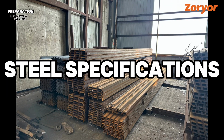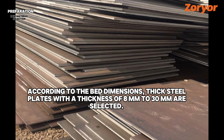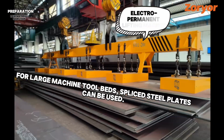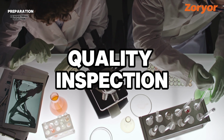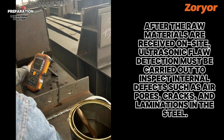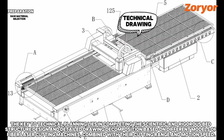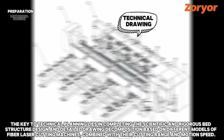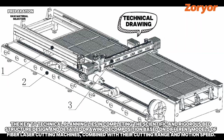Steel specifications. According to the bed dimensions, thick steel plates with a thickness of 8 mm to 30 mm are selected. For large machine tool beds, spliced steel plates can be used. Quality inspection. After the raw materials are received on site, ultrasonic flaw detection must be carried out to inspect internal defects such as air pores, cracks, and laminations in the steel. The key to technical planning lies in completing the scientific and rigorous bed structure design and detailed drawing decomposition based on different models of fiber laser cutting machines, combined with their cutting range and motion speed.